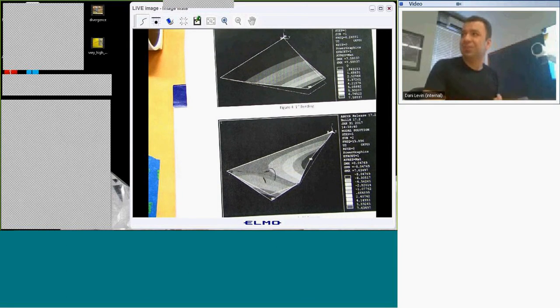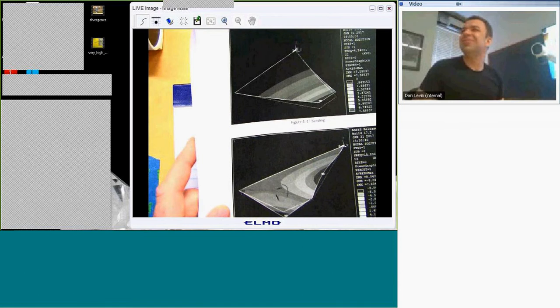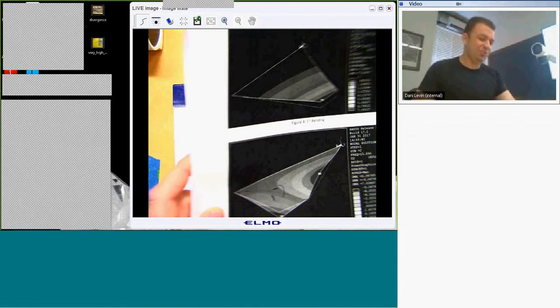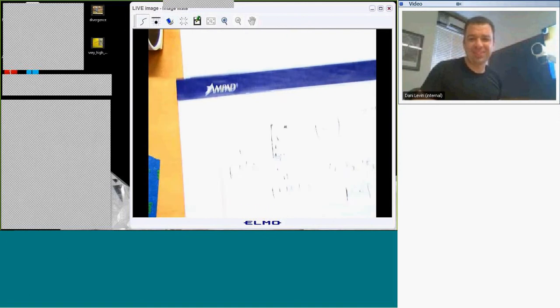Now, if we are getting torsion mode and we have to put our instrumentation on the corner right there. Okay. And if we are not getting any good input from there, we can say that it is not going for bending. It may be a torsion. And when we are going for bending mode, we will see the readings there. Okay, prominent reading there. So we can say that it is likely to go into bending mode.